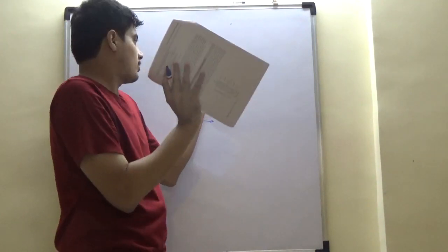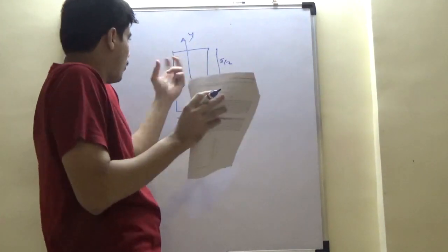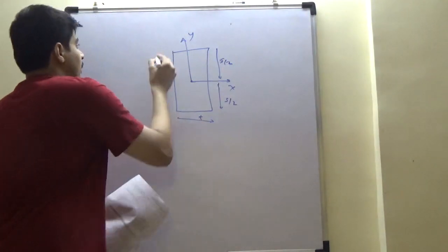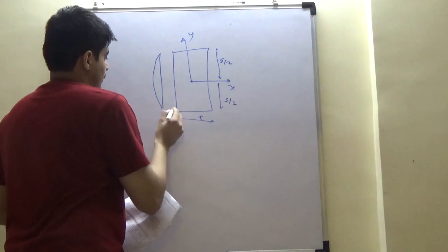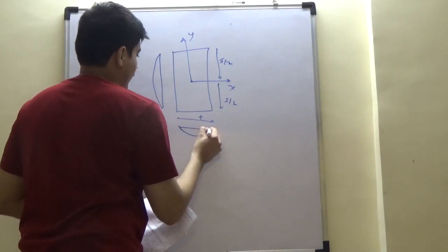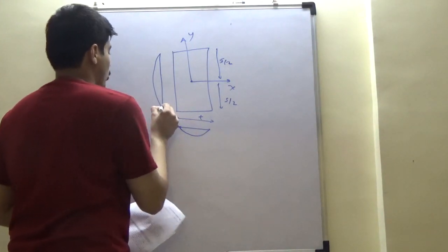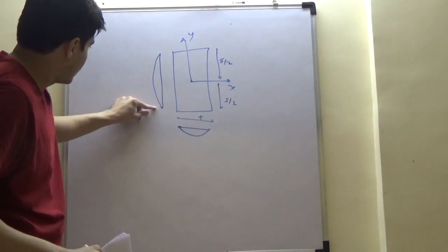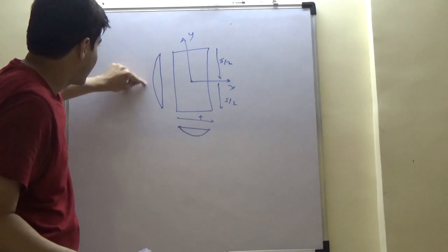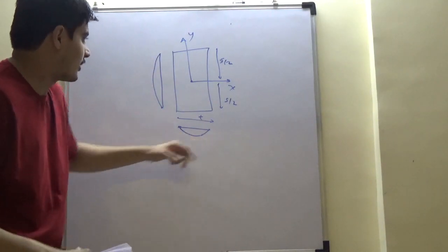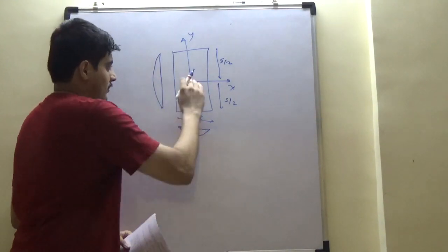There is going to be this twist, and then there is going to be warping which will come out. If you see carefully, since boundary conditions will tell you that they have to satisfy no force, no shear and no strain conditions, the function which we look for in stress or strain will be something like this parabola, maximum here, like a membrane.